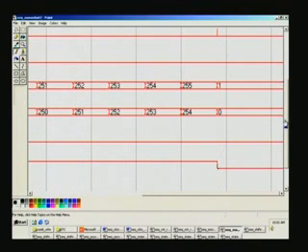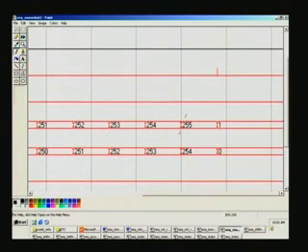And so as a designer, you should be aware of all these things. One slight mistake in the code will make it topsy-turvy, right? And yes. Am I not supposed to have a glitch after 254 also? Here, this is a synchronous circuit, so there should not be any glitch. Glitch will appear only in combination circuit. This appears to be a glitch, but it's not a glitch. It is only acting as per the command that we have given. The instruction that we have given is responsible for this.